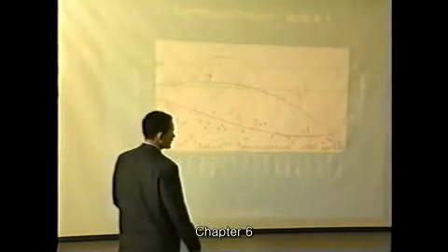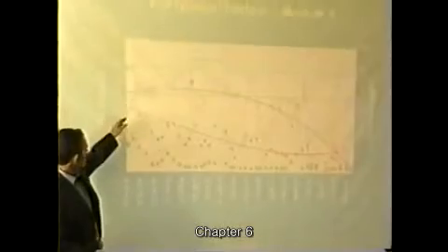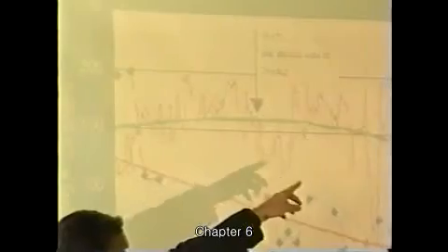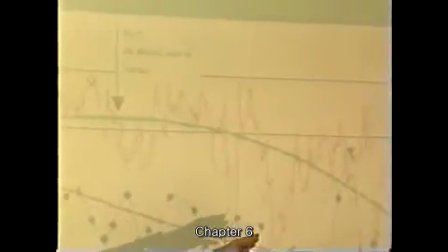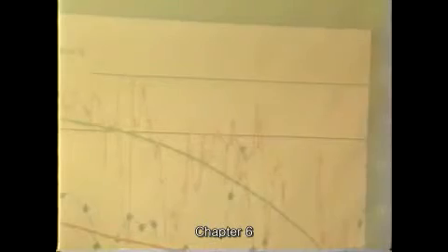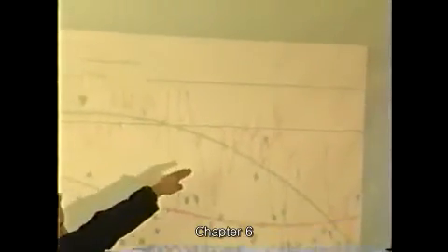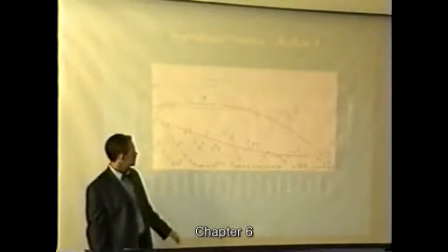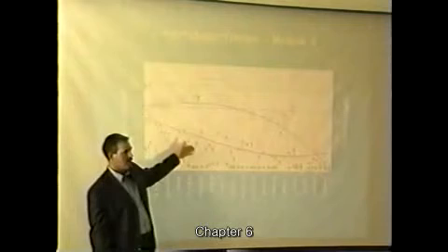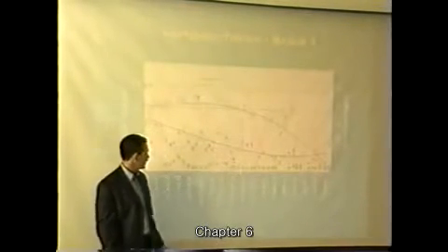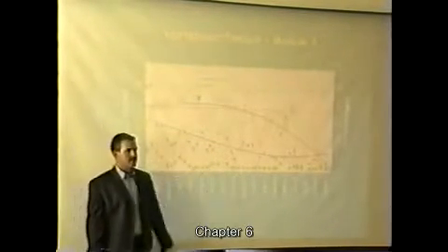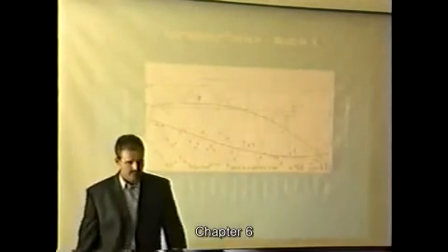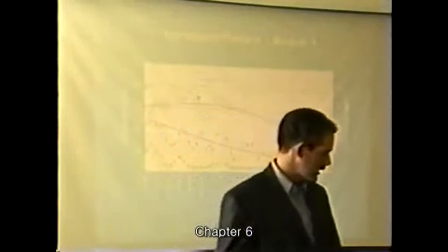And yes, we did. This is typically the ammonia out of their reactor, which is about 20 milligrams per liter. As it comes in, it goes straight out, no nitrification. And as soon as we started, as you can see, the archaea are established in the system, and here the ammonia concentration drops. Similarly, COD concentration is improved. And the bottom one is suspended solids. We dropped that to less than 10, which is a basically negligible amount of suspended solids carried out of your clarifier.